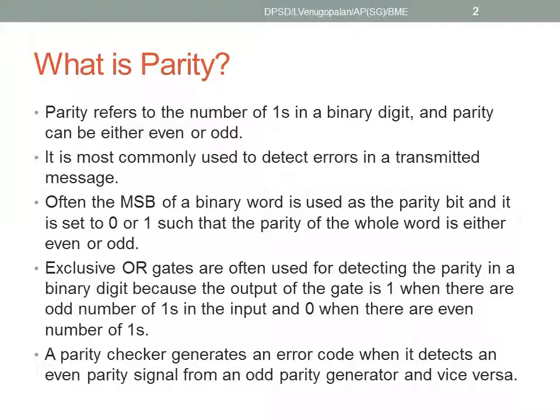Now, what does that mean? You have two circuitries. One is transmitting a signal and the other is receiving. The mode of transmission and reception can be UART, SPI, wireless, anything. So what is the assurance that whatever message I'm transferring is actually the message that is getting received? Because if there is an error, then every other function that is dependent on this message is going to get affected. So we have to be absolutely sure that whatever we are transmitting is getting received properly, and that's why we use these kinds of error detection methods.